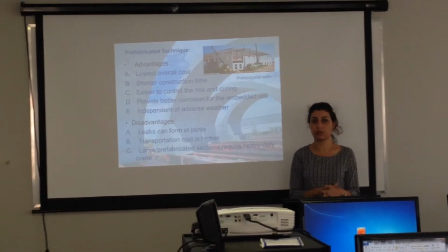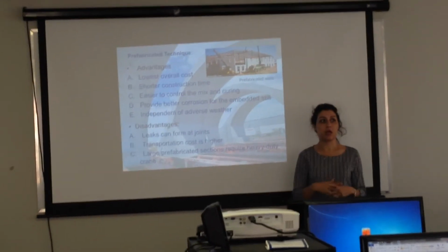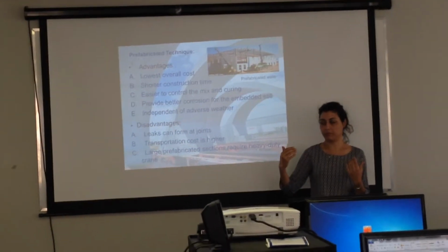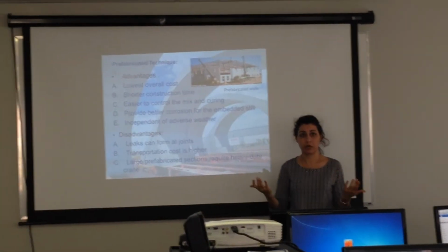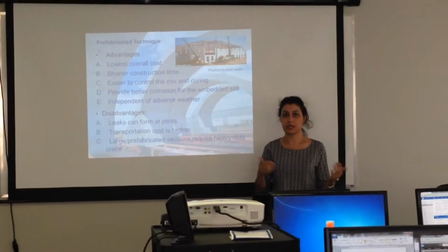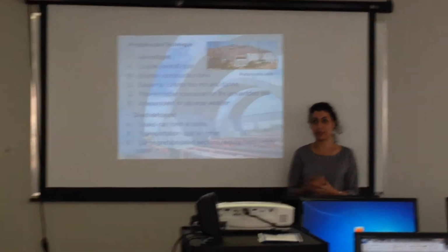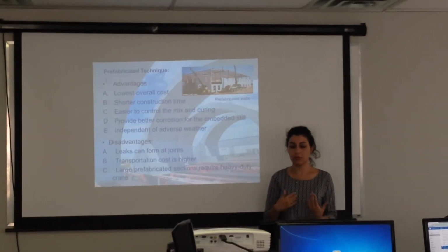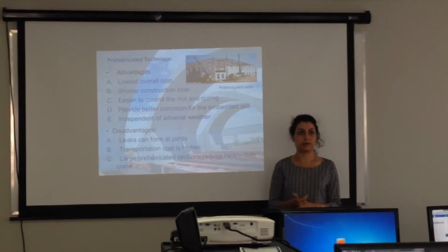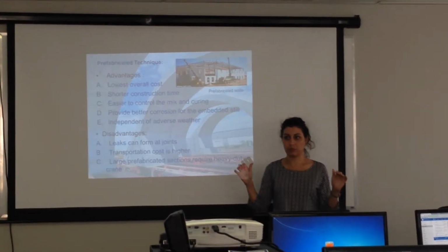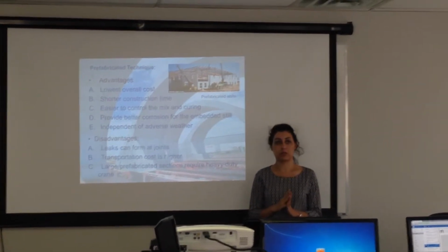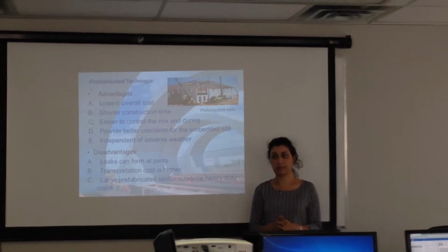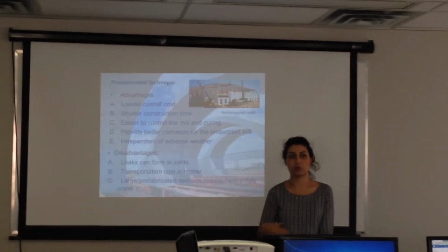Then the transportation cost is higher than the other method, because these elements are manufactured at other sites. Most of the time they are very big, and the number of them is very high, and the transportation cost is added to the cost of manufacturing. The other thing is that for very big pieces of elements, we need a tower crane, whose rental price is quite high. So it's added to the cost of the elements.